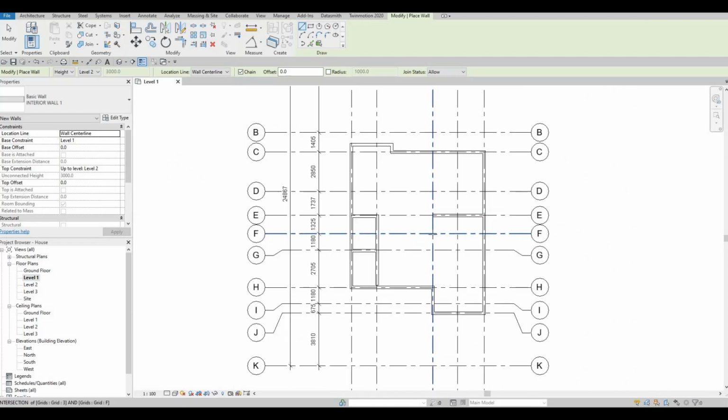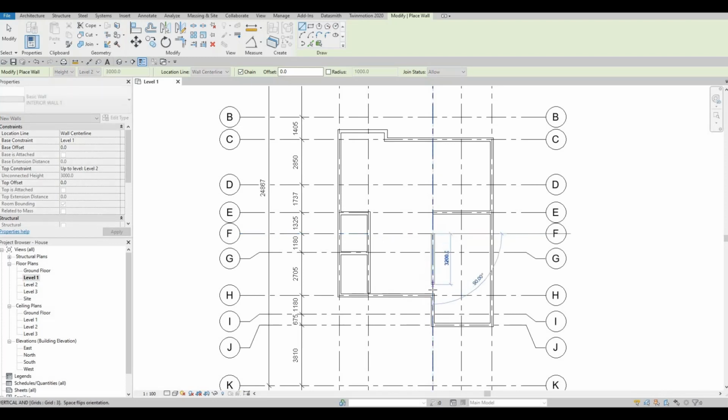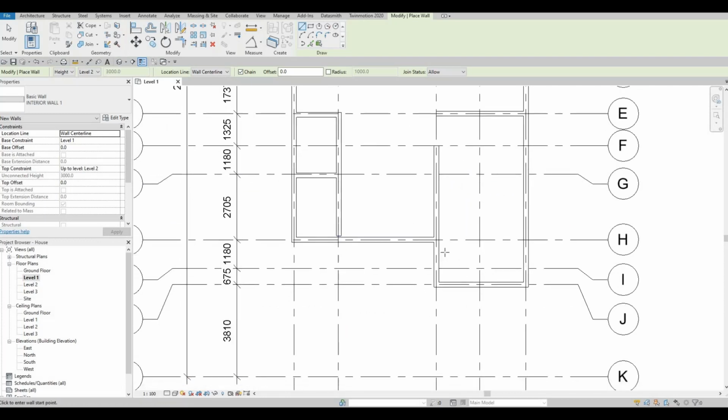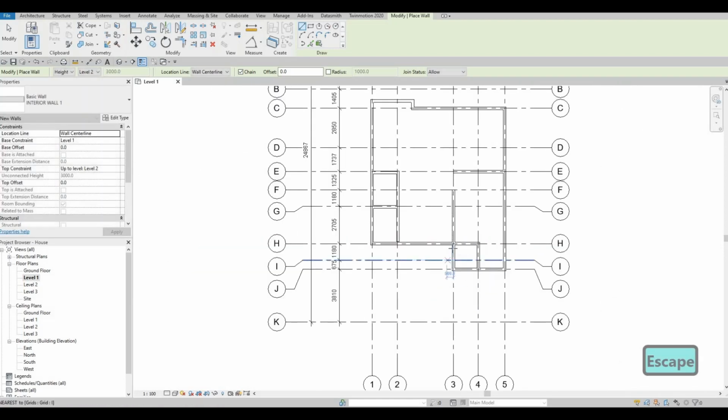So I'm going to add an F3 going up to H3 wall right here, basically extending this one, and we will have our stairs going right here up to the second floor, and then here we're going to close this off for our powder room. So we're going to have it from H3 going to H4 and going down to J4.